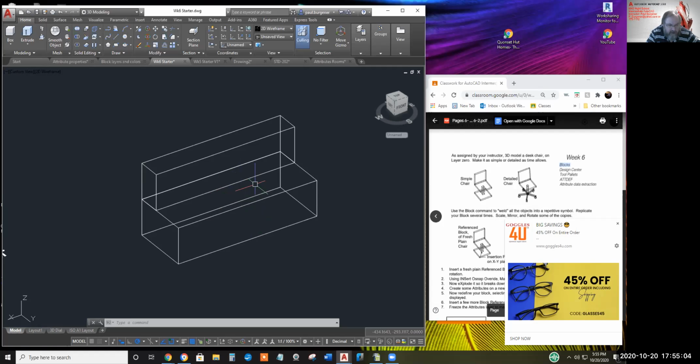If you know the XYZ location of the diesel engine on a sub and you know how much it weighs, and say the insertion point was at its center of gravity, you could calculate how much torque or moment it puts on listing the submarine.